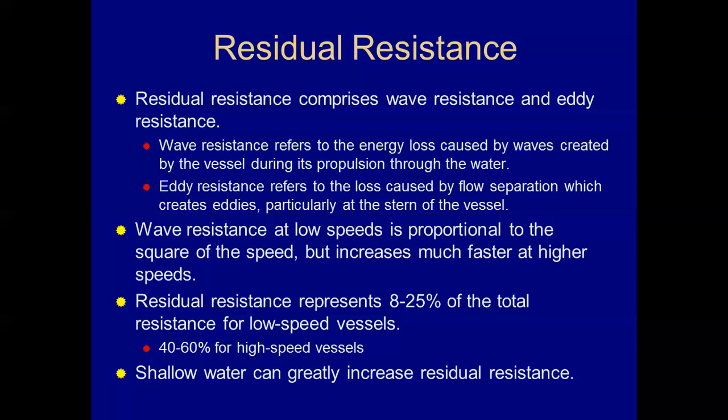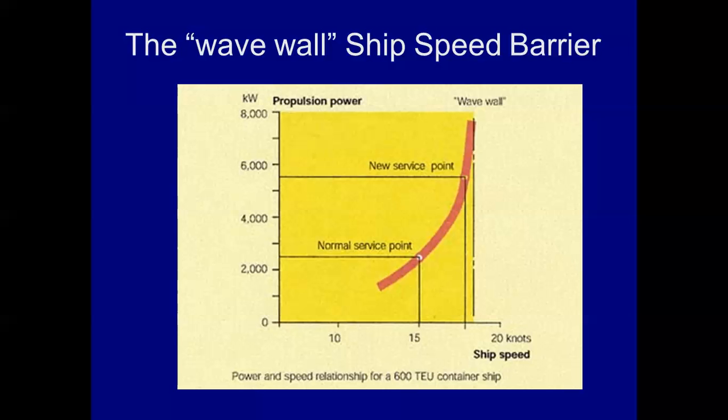Wave resistance will also cause that. As you're going into a storm, it is going to cause the engine torque to increase to maintain your service speed. What this is about too, which is kind of interesting, is that with a certain hull shape, a lot of times just putting more power to it is not going to gain you what you think. Once you get up to a certain point, increasing the horsepower may only give you a small increase in speed.